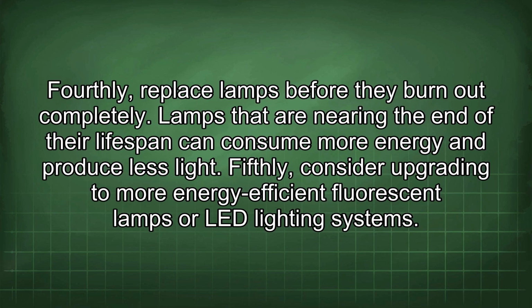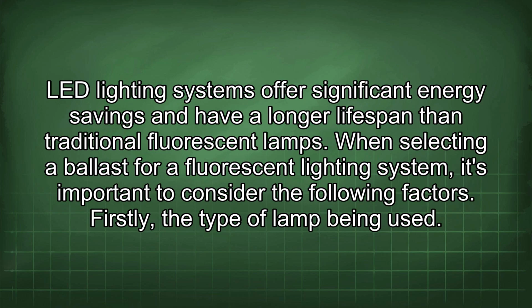Fourthly, replace lamps before they burn out completely. Lamps that are nearing the end of their lifespan can consume more energy and produce less light. Fifthly, consider upgrading to more energy-efficient fluorescent lamps or LED lighting systems. LED lighting systems offer significant energy savings and have a longer lifespan than traditional fluorescent lamps.